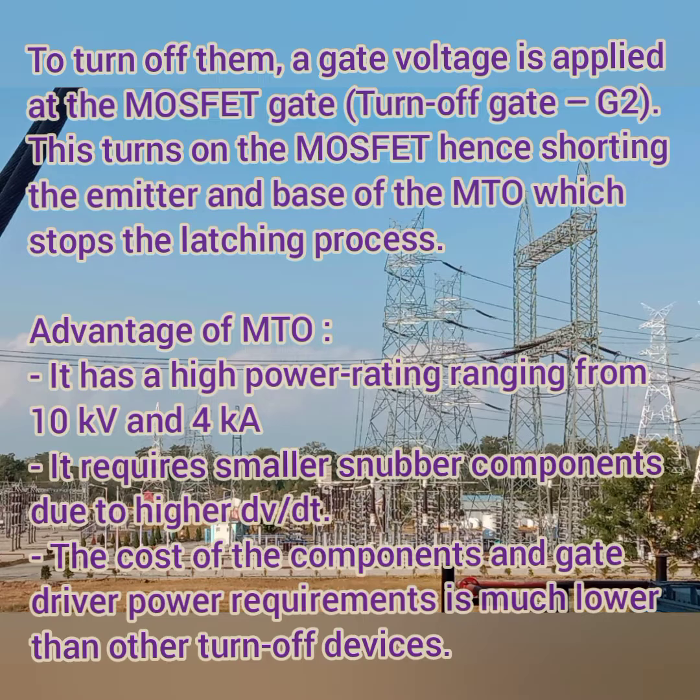So the main advantage of the MTO is it has a high power rating of 10 kV and 4 kA, and it requires a small snubber circuit, which means the snubber circuit is used for protection against high voltage transients. In this case, the snubber circuit requirement is very much smaller. Then the cost of the component and the gate drive power requirement is very much lower than the other turn off devices.